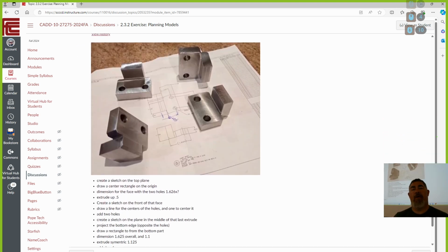On this one, you were asking about projecting? You decided to project, yeah, right here. Bottom edge. Yep. So I said to create a sketch on the mid plane. When you create a sketch on the planes, it does automatically convert edges.